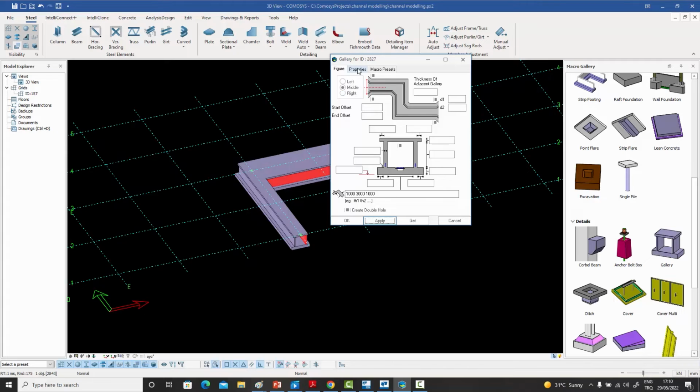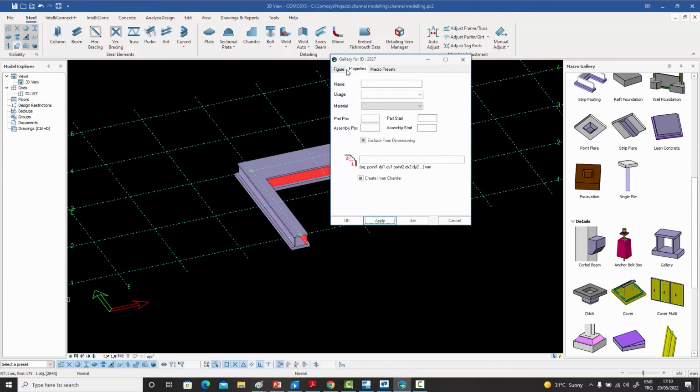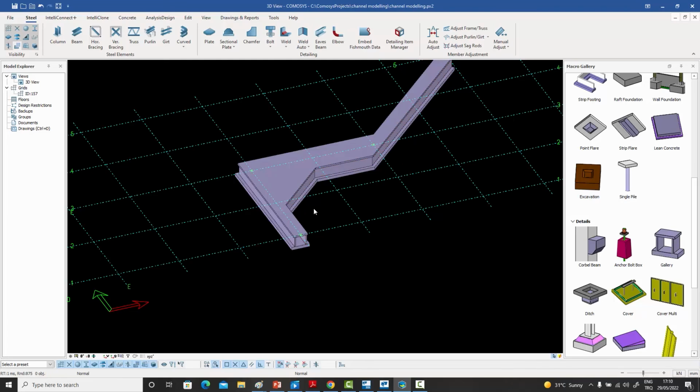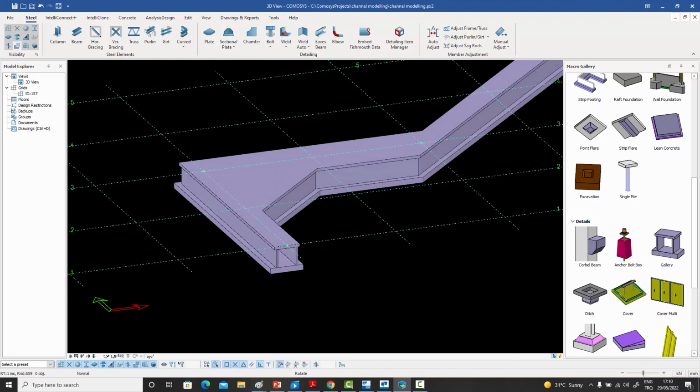So for example, if I were to go to the properties section, and go to the chamfer part over here, I can say give my point number 2 a chamfer of 5,000, and you can give this inside part a chamfer. Sometimes you have this issue of the pipes or the cables not being able to turn easily through sharp corners. So you need to give them some sort of a chamfer for them to turn. So it's very easy to just create this.